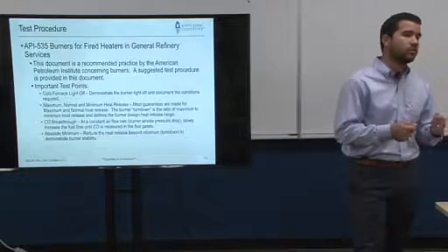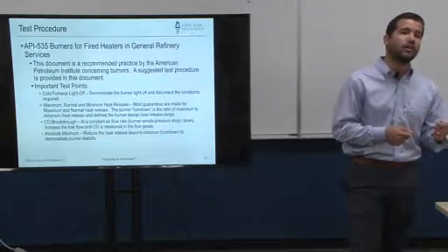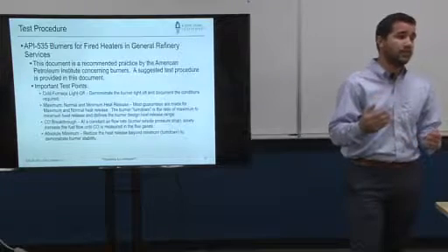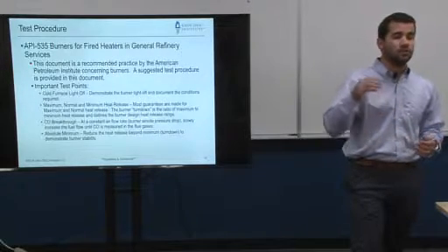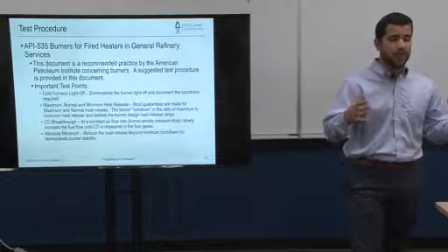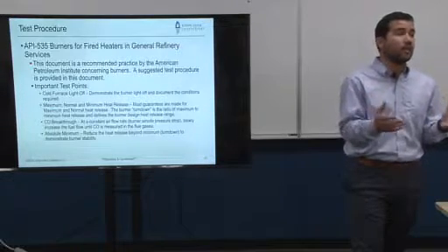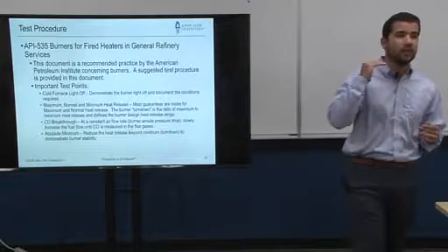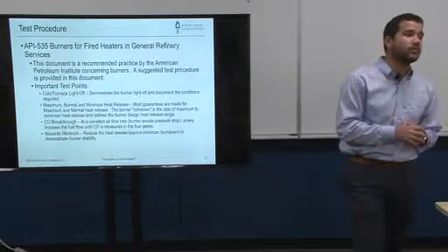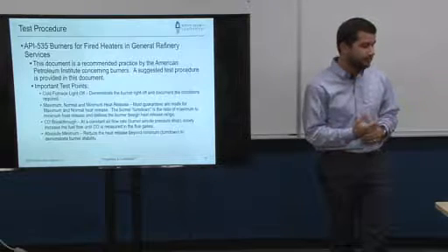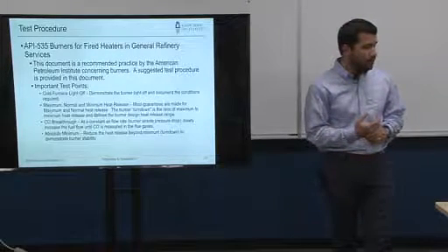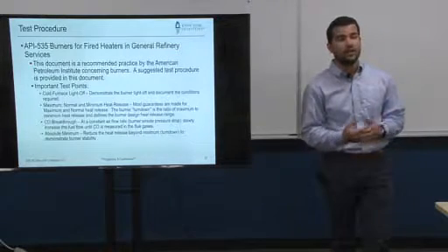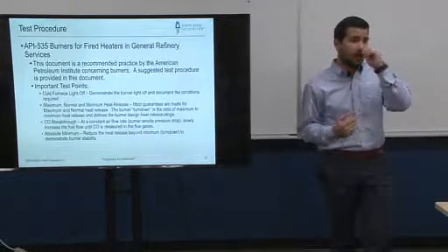The customer really wants to understand at what point you will start forming CO. That's actually used for things like fuel trip. In refineries, they typically have a monitor that looks at the fuel pressure, and once it goes past a certain threshold, it will essentially cut the fuel to that particular burner because something else is wrong. This is actually about to change next year. A couple of other data points are going to be added in there.